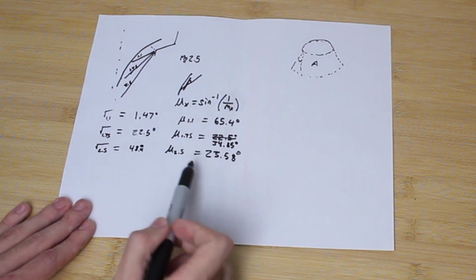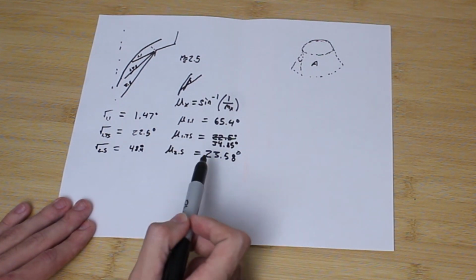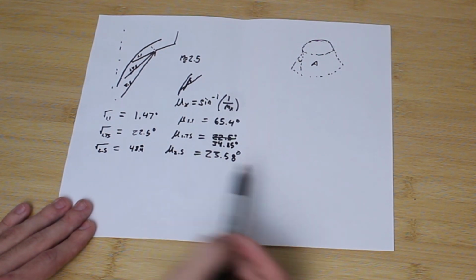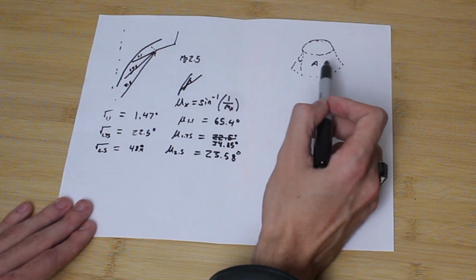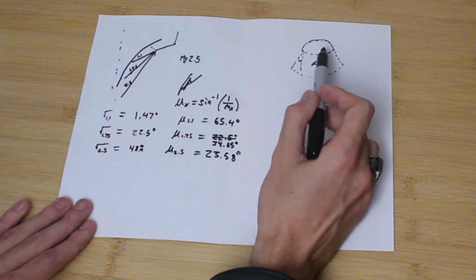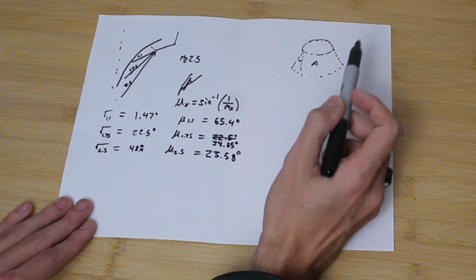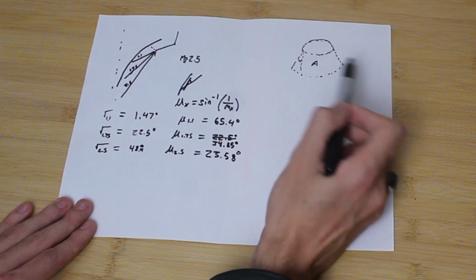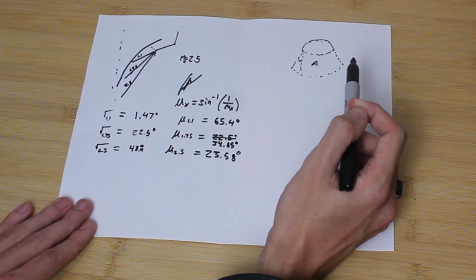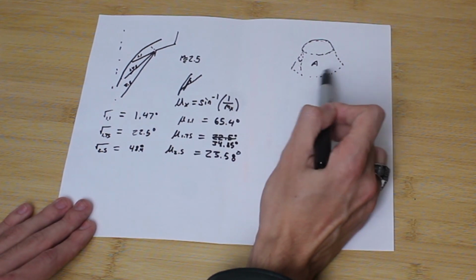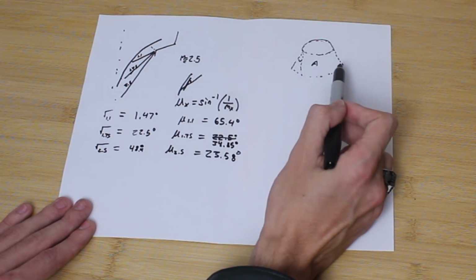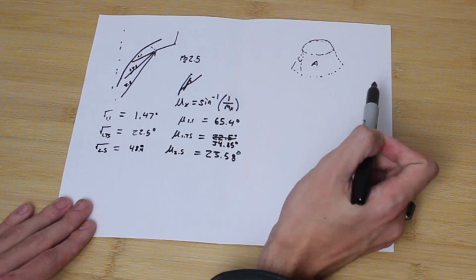Because we know that angle right there from calculating the Mach angle, that will let us calculate the area of the frustum, and then by knowing either the diameter of the spike or the height of the spike, we can learn everything else about the frustum's geometry, right? It'll give us two tightly coupled parameters, the radius and the height of the frustum.